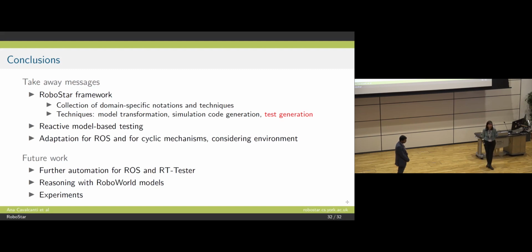They have developed a piece of hardware, a safety platform, which is certified and is dedicated to carrying out the safety functions of a drone. So in particular, for this kind of example, it is going to be doing a bit of the battery monitor, and basically it's going to be polling the communication base, and if it doesn't hear, then it decides there is a problem, I don't want to lose my drone, it needs to land.